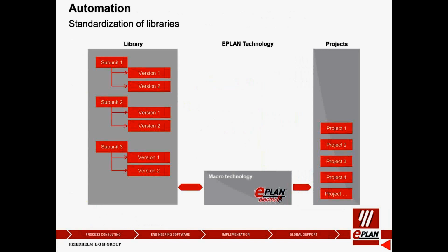So with these different macros available, what we can start doing inside EPLAN is create different variations of different sections of a macro. If we have, as I mentioned earlier, a motor macro, a motor line, we can actually create a second, a third, a fourth, a fifth, and up to 16 possible variations for this motor line. What this benefits us when we're creating a project is that, with the capability of our macro technology, we will be able to produce our projects very easily, because it's a similar case.